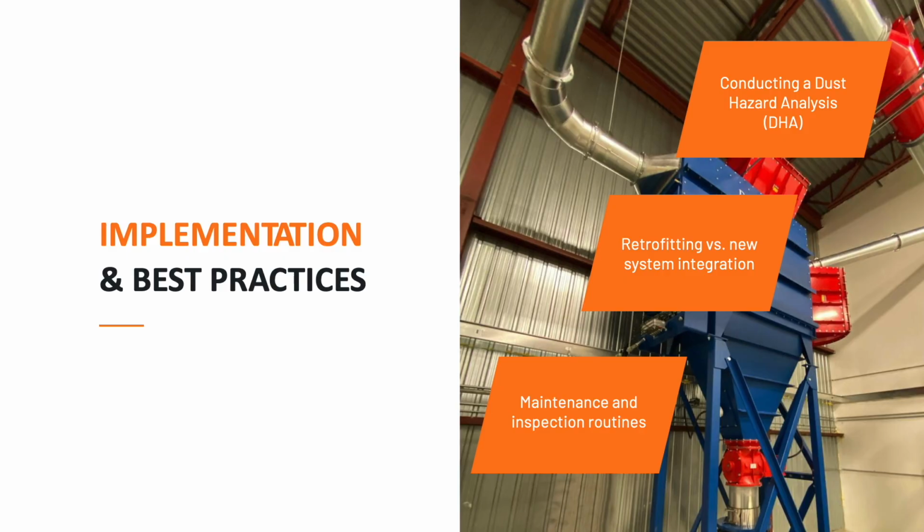Typically, just as a broad overview, if you have a dust collector and you have combustible dust, at a minimum, you need isolation. So that's on the inlet side of the duct. If you're returning air, you also need isolation on the return air side. You need venting on the vessel itself, and you need some kind of explosion rated airlock or drum. All of these things are standard practice. We can pretty quickly take a look at your system and figure out, based on your DHA, what's appropriate. So that's where we come in to help put this system together with the support of Bosch products.